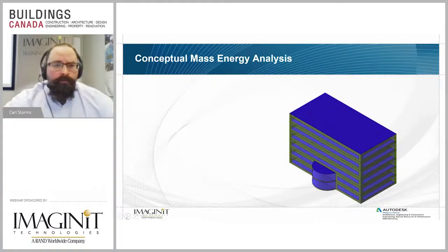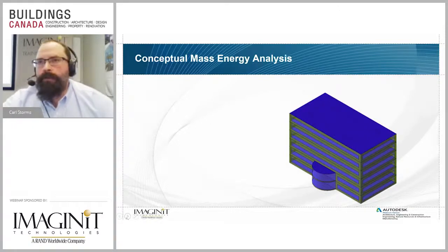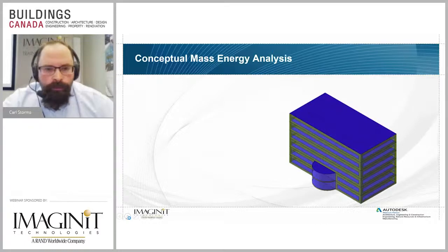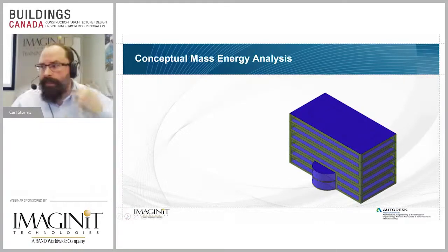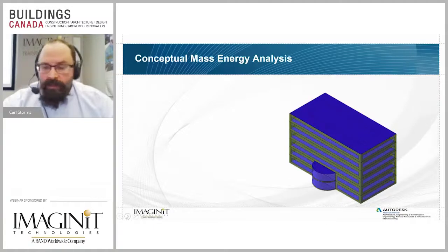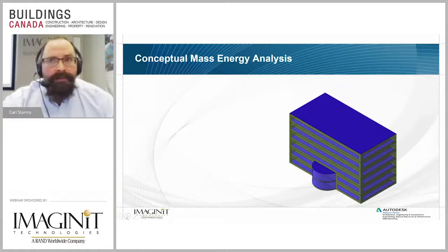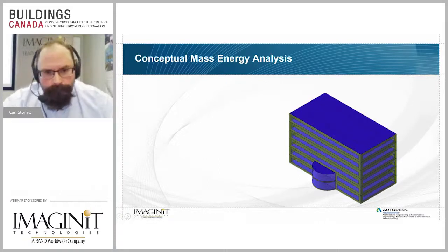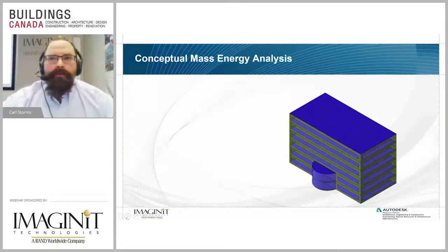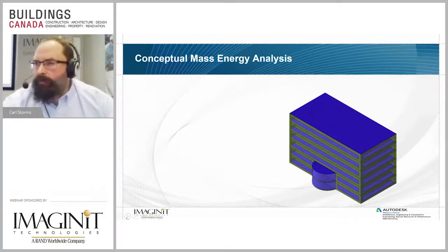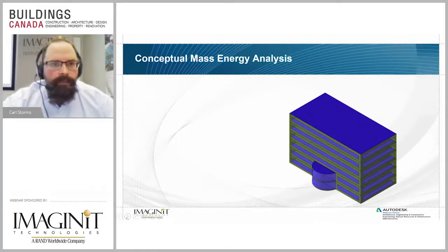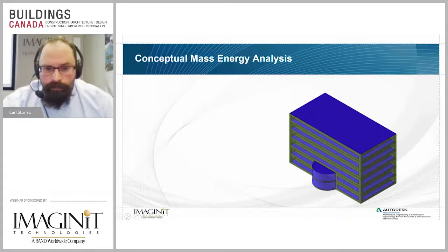So it just looks a little bit different, but it takes some simple assumptions from the model, again, being derived from those thousands and thousands of test cases to give you some information about your particular project. Now, all that you really need in this case to get going is to know where your building actually exists in the real world so that when you bring in your analytic data from the weather stations, it's accurate. And you also want to know that it's located in the proper direction, meaning true north instead of project north inside your elevation. And that's all that you really need to know.